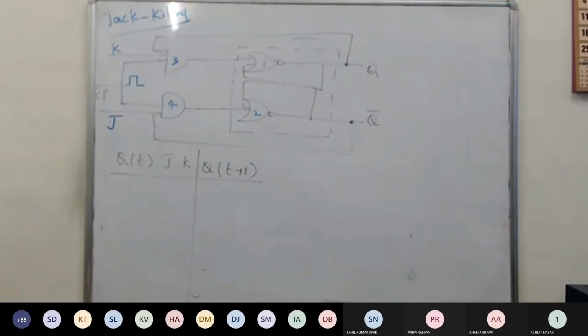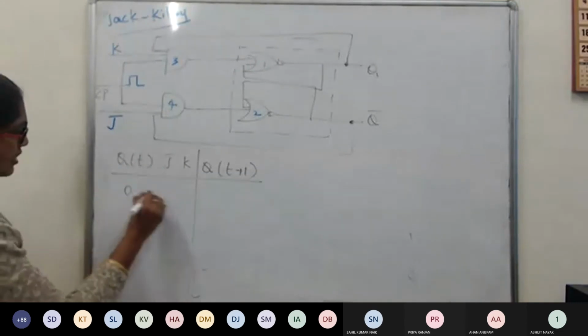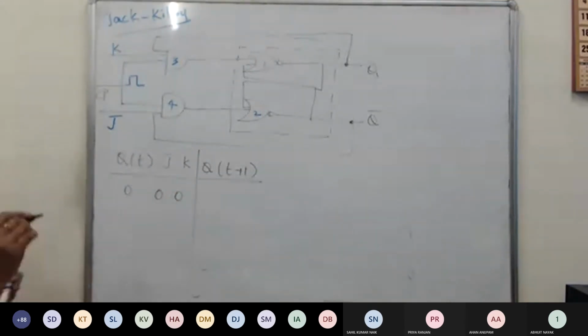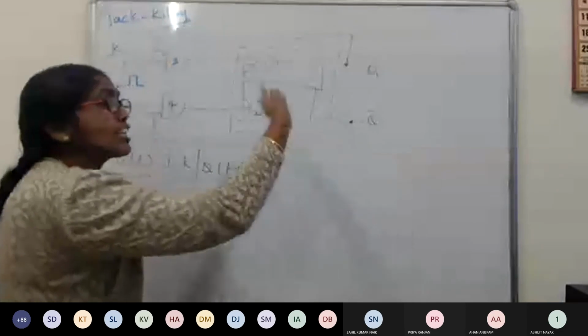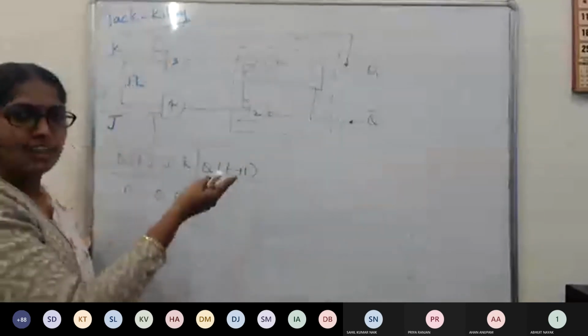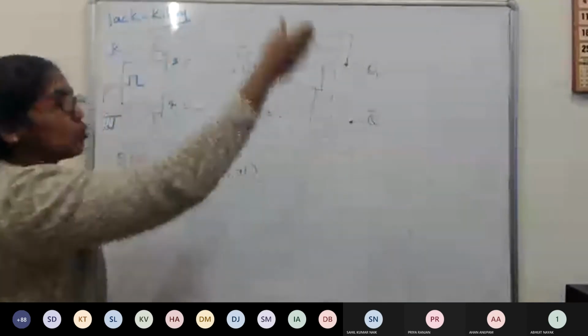Okay, go step by step. Don't get confused. First of all, even if you analyze any portions, afterwards for every gate output you try to write, then evaluate. We have T and T plus 1. I am purposely avoiding Q bar. Why? Because it increases the burden. If at all here we will see again, we might be pushing to T plus 2 state. So that's why I am avoiding writing Q bar. It's a good habit. If you don't write Q bar, the analysis is very easy.